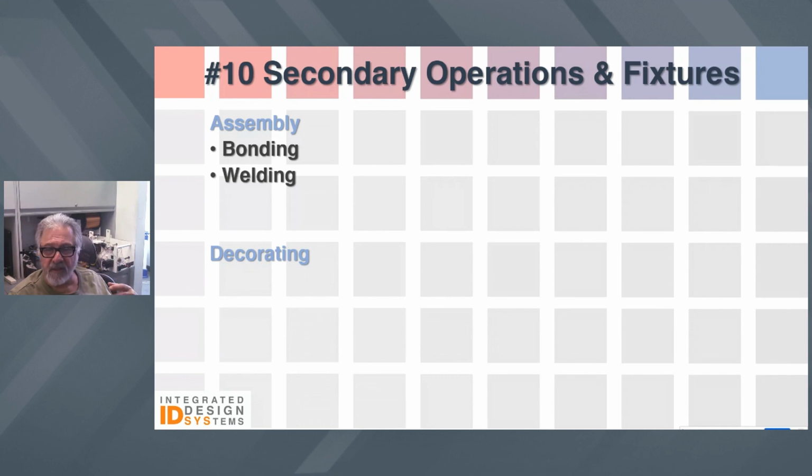Then there's the potential of welding parts, especially semi-crystalline materials, which are difficult to bond, like polyethylene or nylons or acetals. These materials are sometimes difficult to bond, so they're more easily welded together, if it's possible. And the welding could be done either by literally using a hot air gun, or ultrasonic bonding, or spin welding, or hot plate welding, all these different assembly methods.